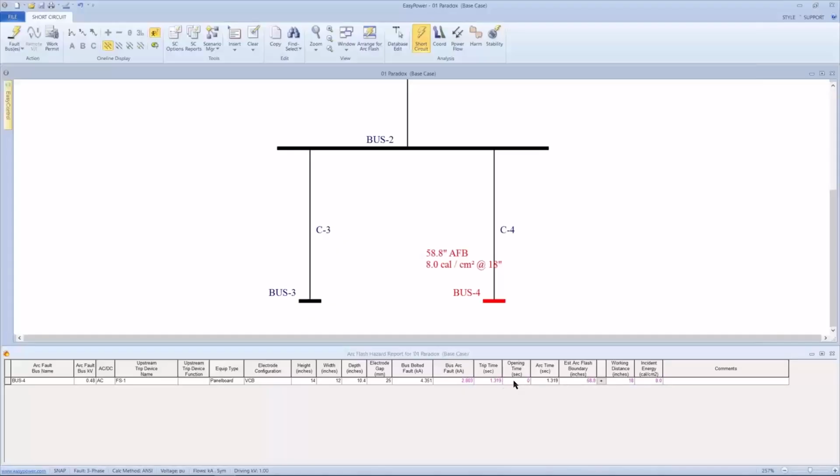And consequently, if I'm wearing the 4-calorie PPE that I used when I was working on the transformer secondary, and I come down here, I'm going to select these and compare these two results. And come down here with my 4-calorie PPE and accidentally induce an arcing fault, my exposure to the arc will be greater than my PPE rating, and I may not be in a safe condition under those circumstances. And so both the electrician and I went, duh, I get it.